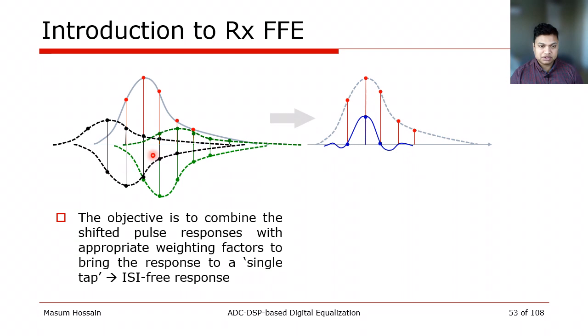This happens because, as we see, it's a spread out pulse. It means when I was subtracting the post cursor, some amount of precursor was there that was pulling down my main, and the same happened when I was cancelling the precursor. So this reduction in the main can also be viewed as a signal power reduction or SNR degradation that will be discussed further later on.